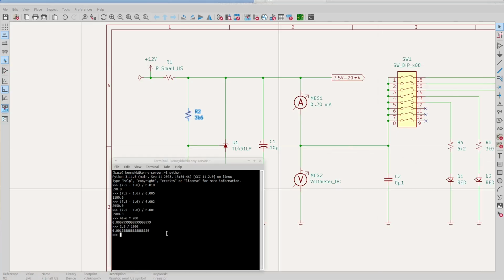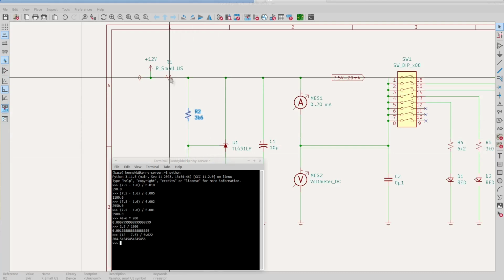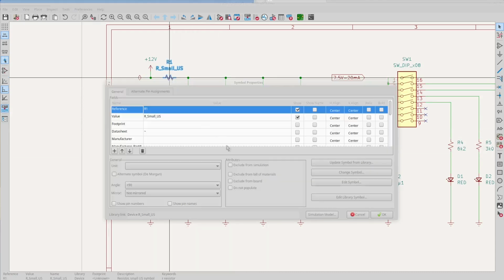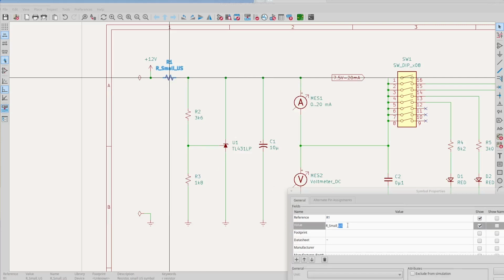Finally, we need to size the current limiting resistor. The load will draw up to 20 milliamps. The TL431 itself, according to the datasheet, will draw 0.6 milliamps. The voltage divider will draw 1.4 milliamps. That's a total of 22 milliamps. 4.5 volts, the amount that the resistor will drop, divided by 22 milliamps, is 204 ohms, so a 200 ohm resistor will be about right.